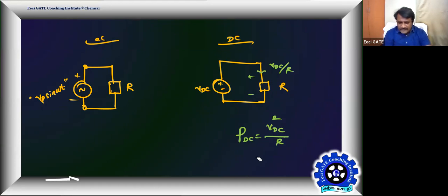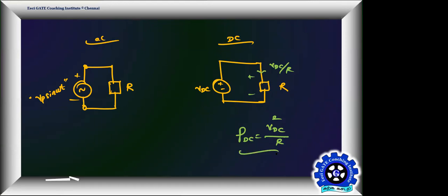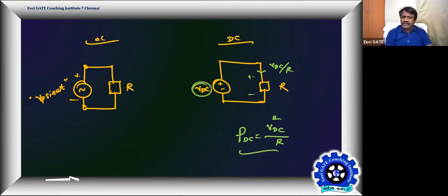Yes, sir. Instantaneous power is going to be your average power because nothing is instantaneous. This is a constant. Voltage is constant, current is constant. It's not a periodic signal. It's a signal forever from time t equal to 0 to infinity. Therefore, this is the constant power it is delivering. Average for DC doesn't make any sense. That's a constant power it is always delivering the moment you turn on your DC power supply. So that's the effective power delivered by the DC source.